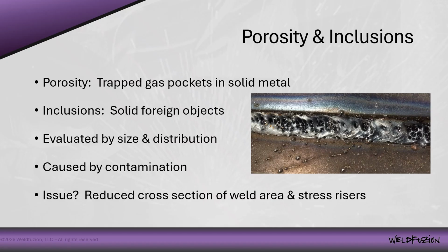If we determine it has good weldability, we could assume the base metal or the filler metal may have been contaminated and not properly cleaned or stored. We'll talk about sources of contamination in each material section so you'll know what to look for and what matters on each specific material as it comes to weld quality in your shop.